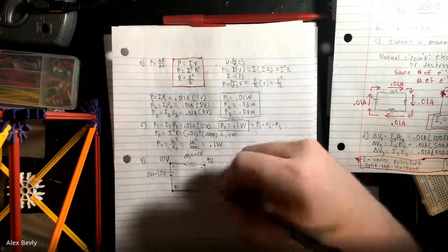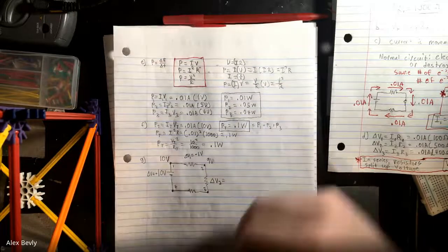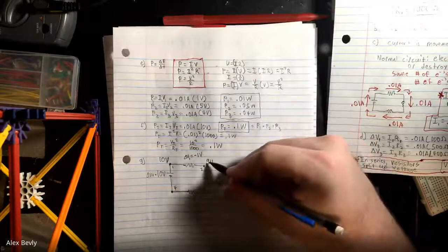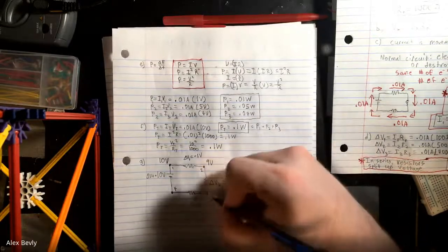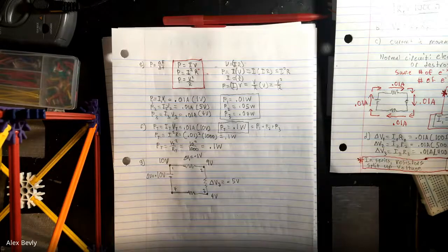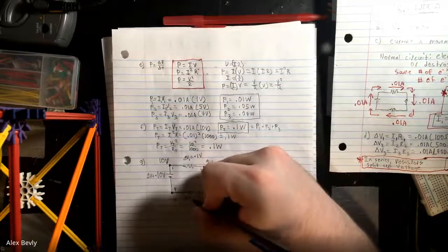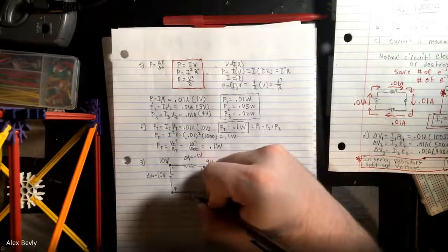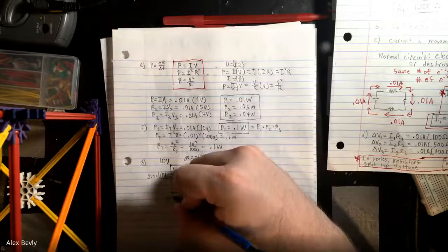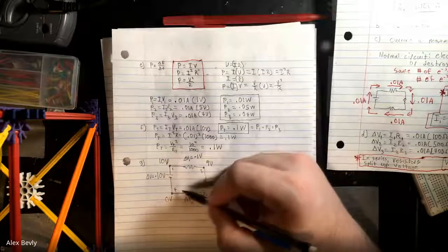And then I get to resistor 2. The voltage drop across 2 is 5 volts. So I lose 5 volts. So I had 9 volts. I lost 5 volts, so I'm down to 4 volts. And then my voltage drop across 3 is 4 volts. So I lose 4 volts here. I had 4 volts, I lose 4 volts, so I'm down to 0 volts. And then just like that, I'm back down to 0, I'm back down to my ground state before I add more voltage back here.